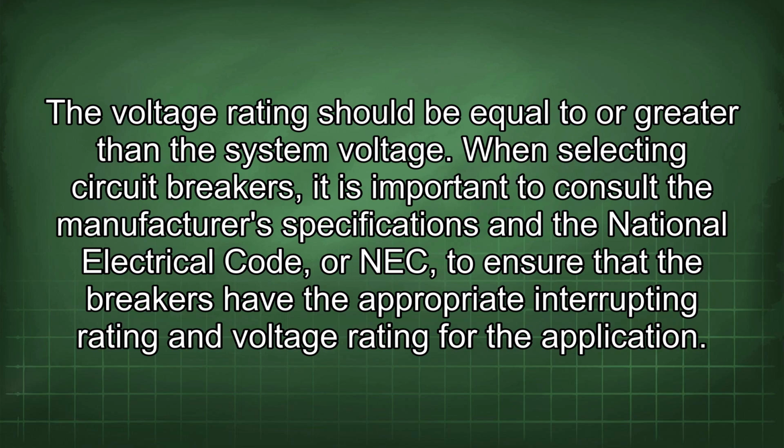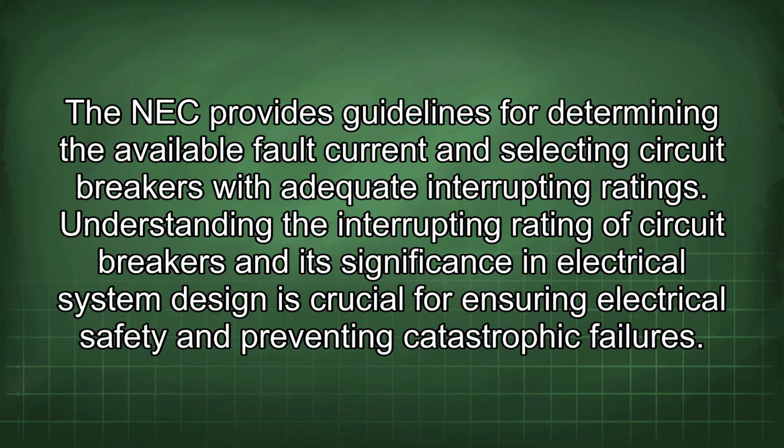When selecting circuit breakers, it is important to consult the manufacturer's specifications and the National Electrical Code, or NEC, to ensure that the breakers have the appropriate interrupting rating and voltage rating for the application. The NEC provides guidelines for determining the available fault current and selecting circuit breakers with adequate interrupting ratings.